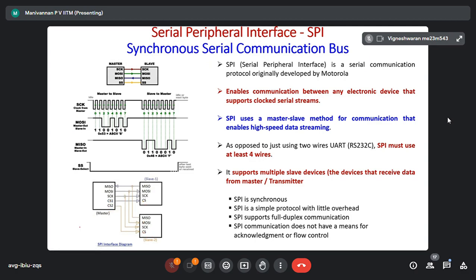Another thing I want to show is, please see that this is data, and this is called clock. The data is first sent, correct? This is the data duration. For example, this is 1. The first bit is 1. So you can see that this voltage is high. This is 5 volts. Which pin? MISO pin. MISO pin equal to 5 volts during this period.